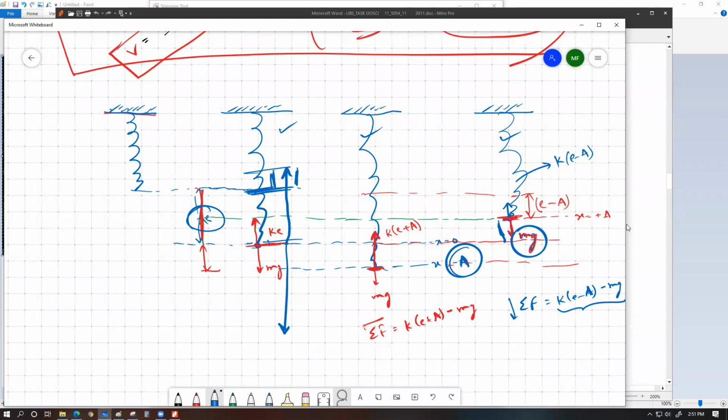So you can have a bit of different equation for that scenario. In that case, the spring is going to push it down for this much. Let's say this distance is, I'm going to write, let's say D. So when the particle is in the topmost position, the spring force is going to work downwards. The weight is also going to work downwards. So for that scenario, the resultant force for this position is going to be working downwards, and the magnitude of this force is going to be K into D, which is the actual compression of the spring, plus mg.